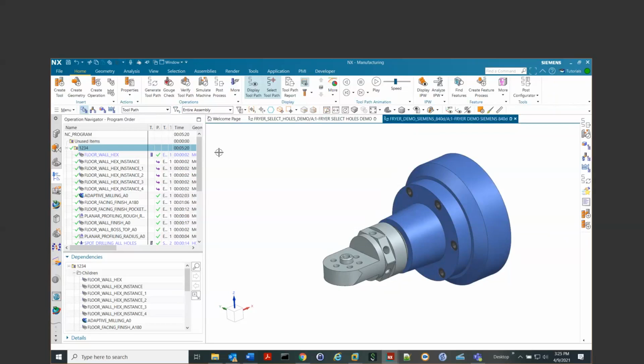On some machines it's a little trickier, and it really has nothing to do with the SINUMERIK control. It has everything to do with how the machine was commissioned. Some OEMs, some builders, like to do some pretty custom stuff, and if they don't think about the inch metric scenario and validate its current state at any given point, then they can run into traps.